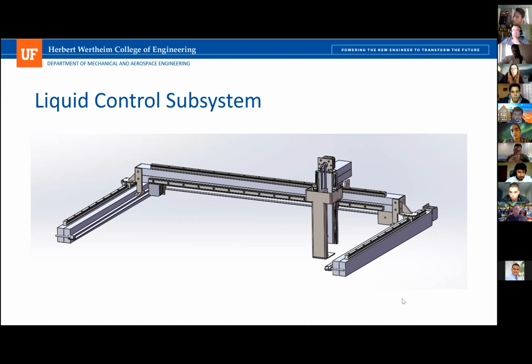The way to potentially minimize misalignment errors could be to have close fit attachments. We're using 1/4-20 screws, and with a close fit, we're able to make those holes in a line and ensure that it moves smoothly throughout the assembly.